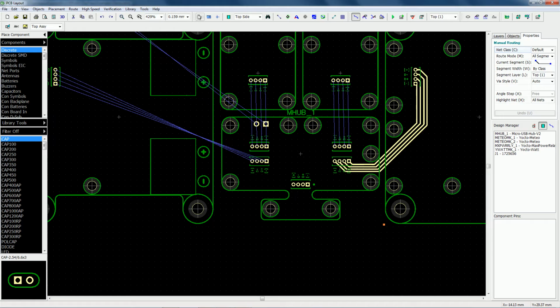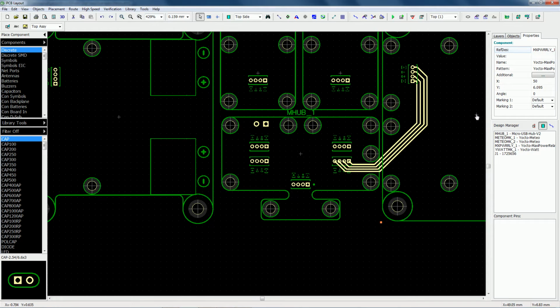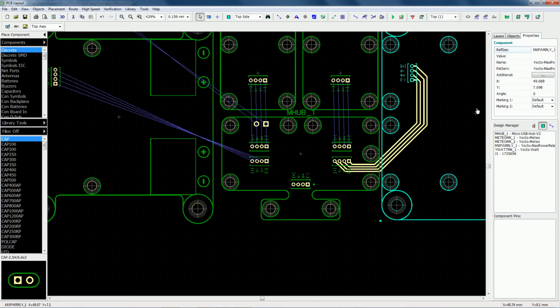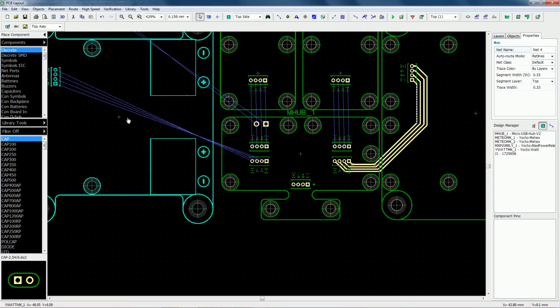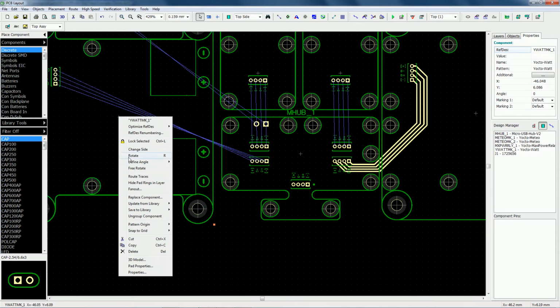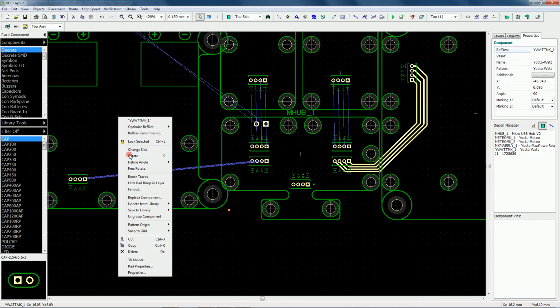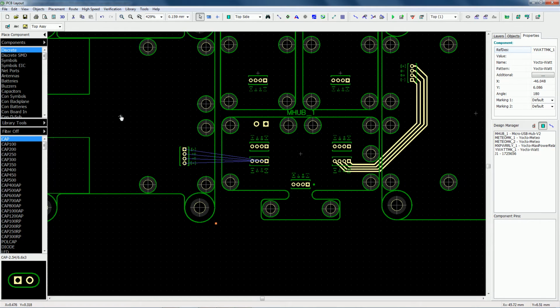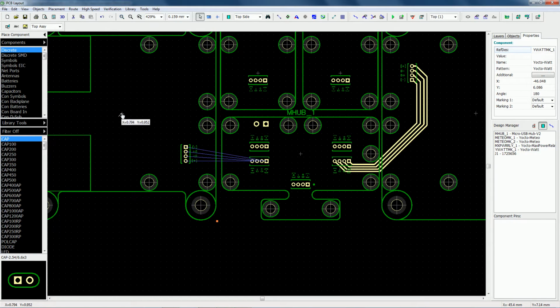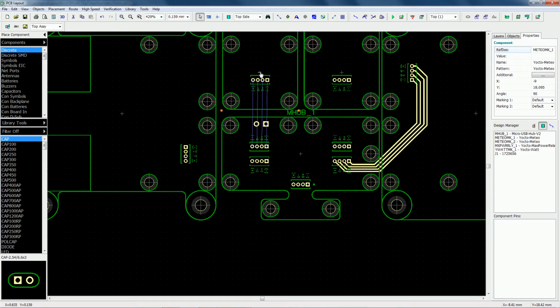As you can see, the device was not well aligned, so you can still move devices a little bit. You'll see that the tracks move along a bit, but this can create shortcuts, so be careful to edit the track afterwards if you move a device. Now, we're turning this device as well, since it was not in the right orientation, and we'll align also these others, as we see from the blue lines that the devices were not completely well aligned.